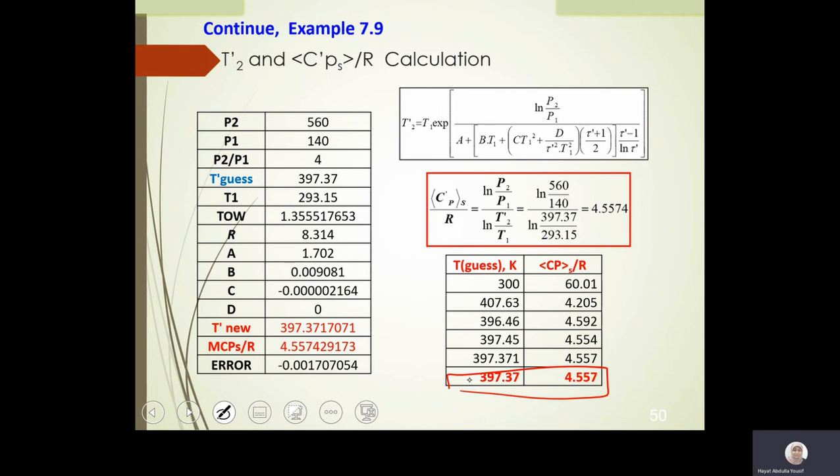If they want the entropy, again, I will bring the entropy equation and I will substitute here. Cp ln T2 over T1 minus beta V delta P. All the information were given. V, we found it from the table as we mentioned previously, so it's just a matter of substituting. Plus, and delta S, we get it as 0.09 kilojoule per kilogram. I'm done with the pump, and these are the nature of questions that are normally given.